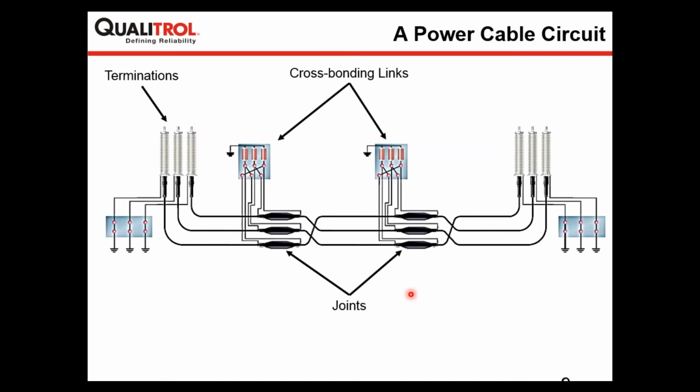But if you have middle groundings or T-joints, then you need to access each cable shield at different joint positions so that you will be able to zone partial discharges in different sections of the power cable. That is the maximum you can do if you have middle grounding or complex T-joint networks, which normally happens in the distribution network.